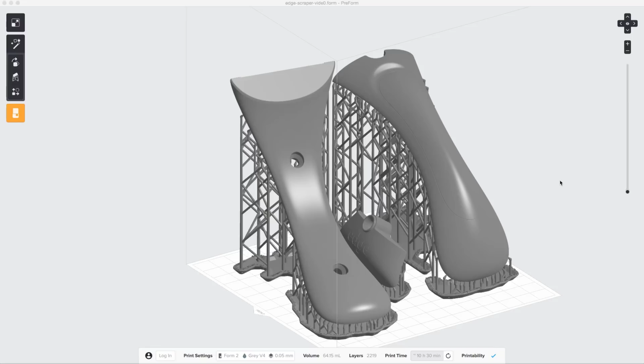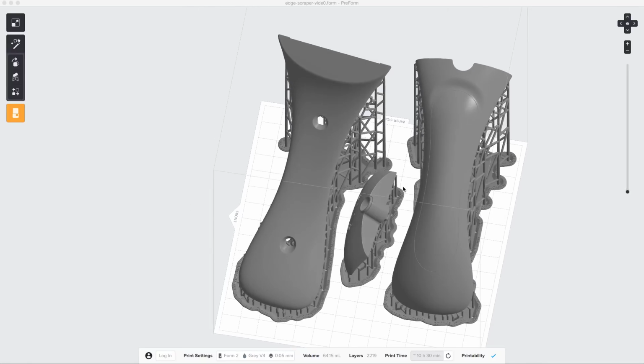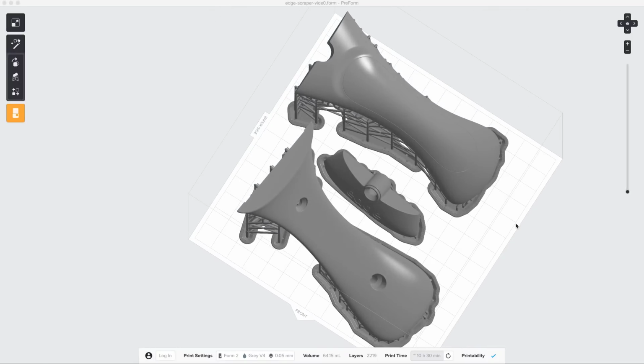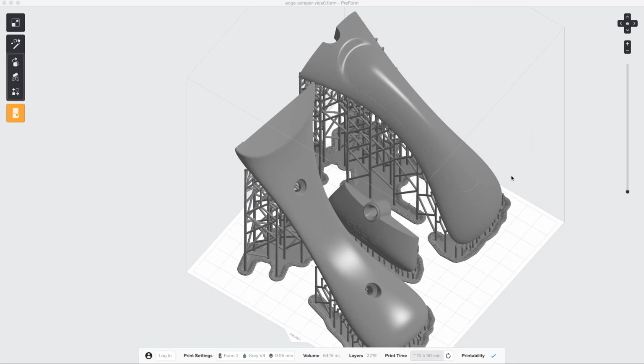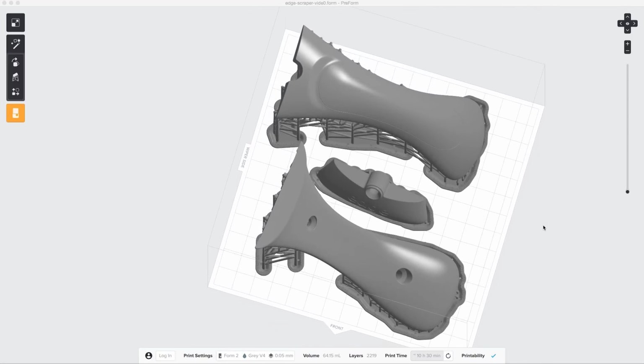Having oriented and supported the model, we can now check the slices of the build and calculate the print time. As we move around the model, we can see that the part orientation is good, thus promoting a good flow of resin during the build. The tallest supports are adjacent to the wiper side of the printer, and the parts are horizontal to the front edge.